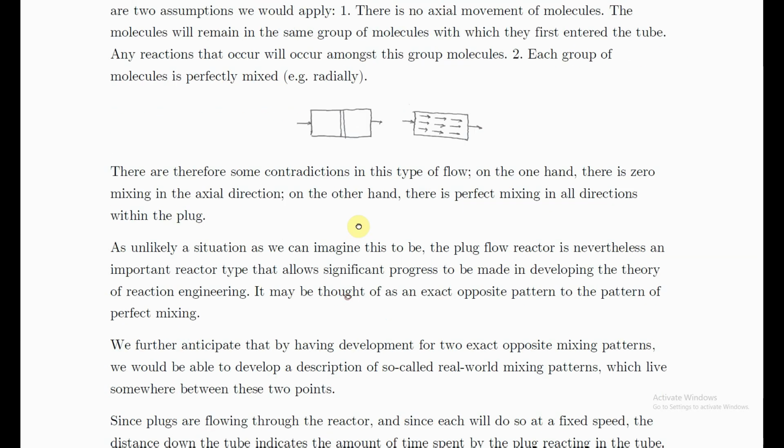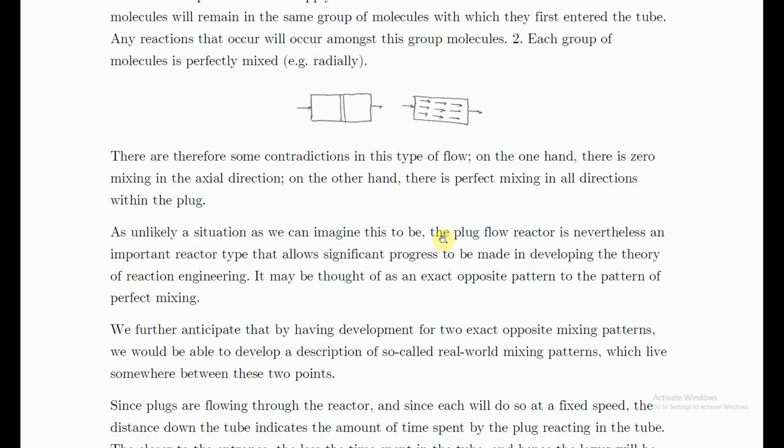And then yes, you might think this is an unlikely situation, that it's hard to accomplish such a kind of behavior, that it's hard to stop molecules diffusing around. And definitely you can't stop them diffusing around. But if you have a high enough flow rate here, if your fluid is passing through this reactor fast enough, then it's possibly the case that there isn't as much time available for diffusion to deform where the molecules are sitting.